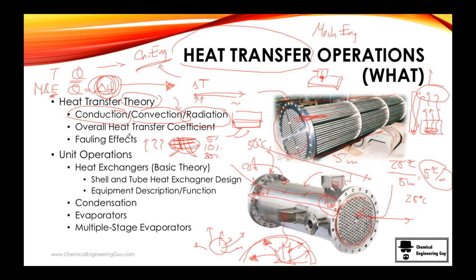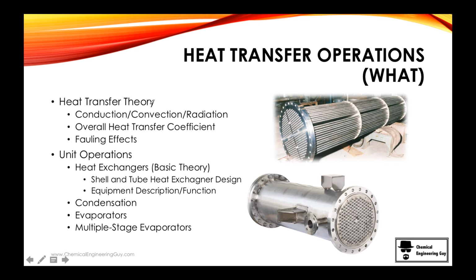Now that's the theory behind it. Then we start analyzing the overall heat transfer coefficient for this. You will probably see here a tube, and we have plenty of that. We have the interaction of fluid and wall, we have the wall-wall interaction, and we have wall and inside fluid. So there are 1, 2, 3 layers.